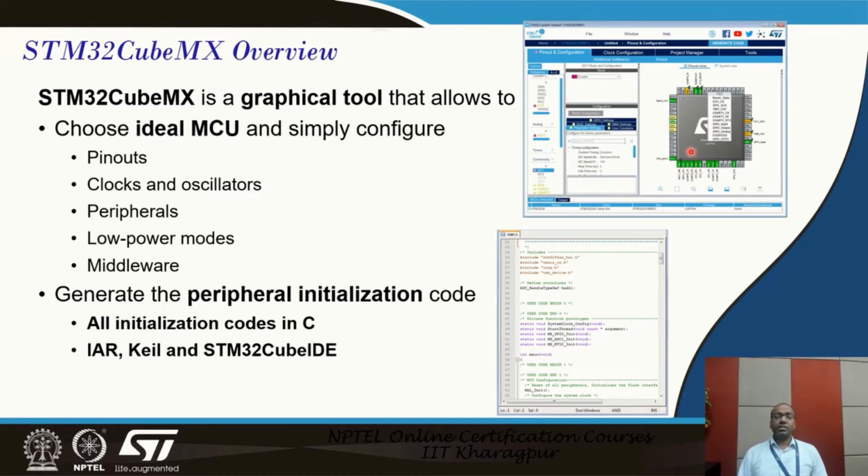The most important thing, the initialization code: it generates the C code and it generates the project for three different IDEs. The first one is IAR, the second is Keil, and the third one is STM32CubeIDE. STM32CubeIDE is open source.